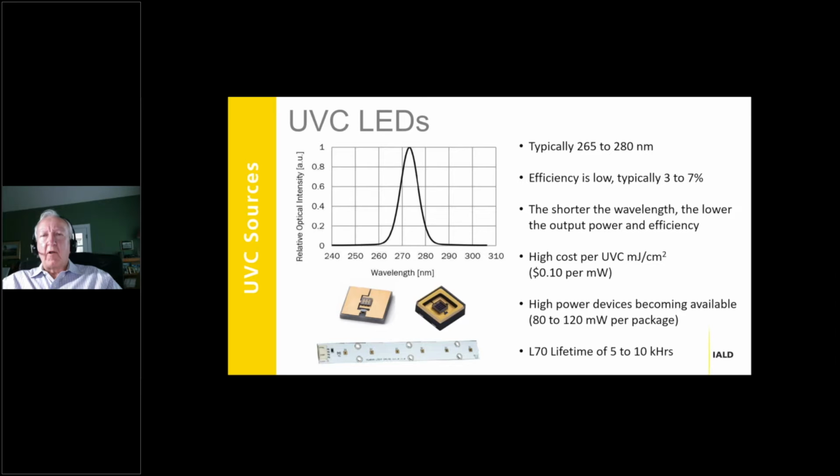Now, just like all LEDs, designers using UVC LEDs in germicidal systems will need to worry about binning and lifetime when designing a UVC LED germicidal system. Another big difference between UVC LEDs and their blue LED cousins is that the lifetime of UVC LEDs is considerably less, with L70s typically less than 10,000 hours. That will need to be factored into the design of lighting systems that have a UVC component, because the UVC LEDs will just simply not last as long as the solid-state lighting LEDs will for general illumination.